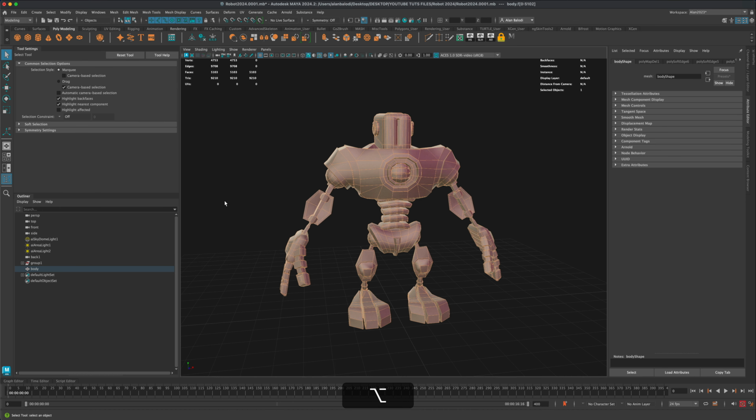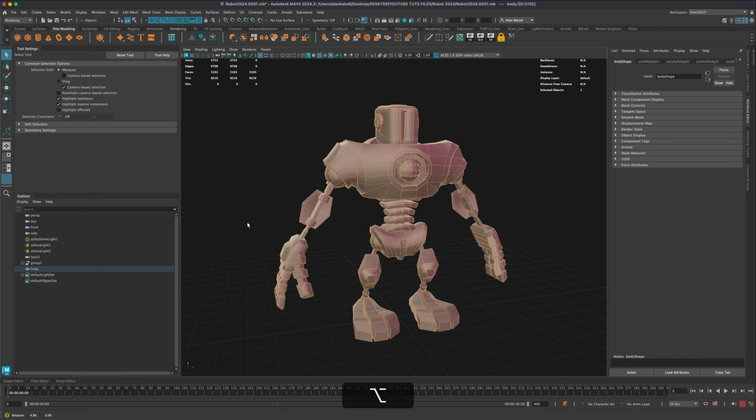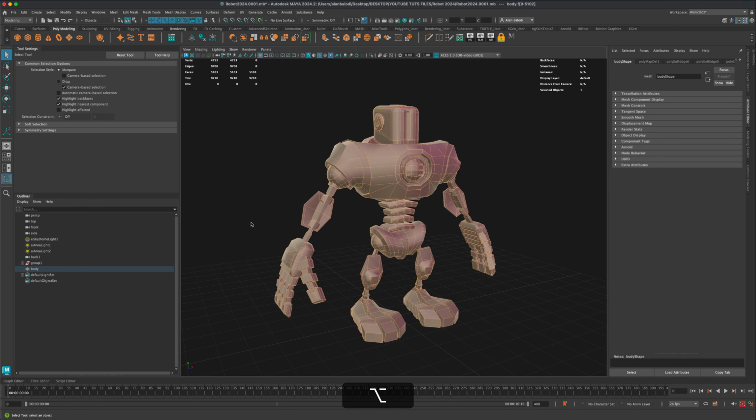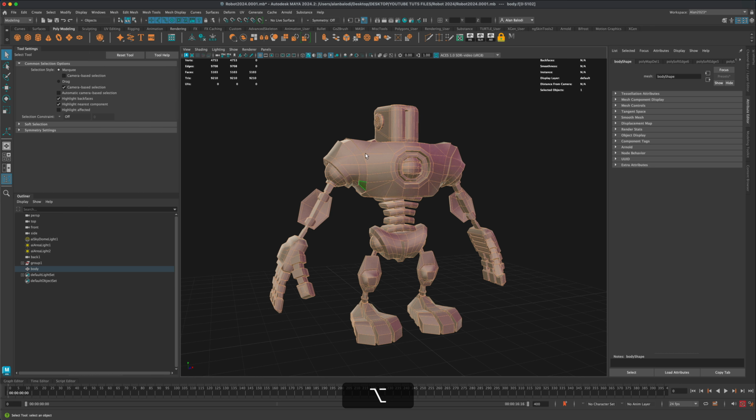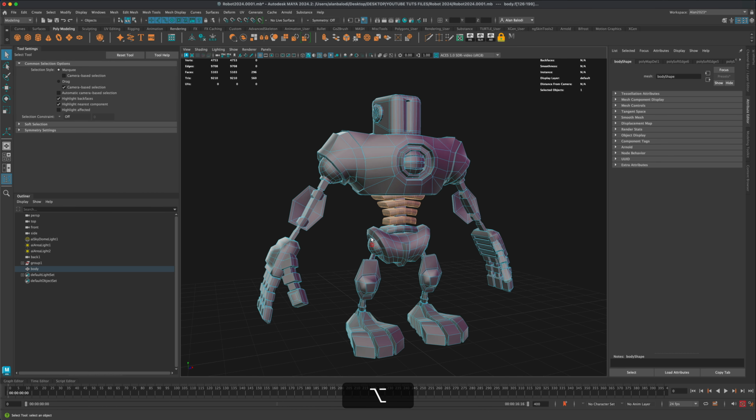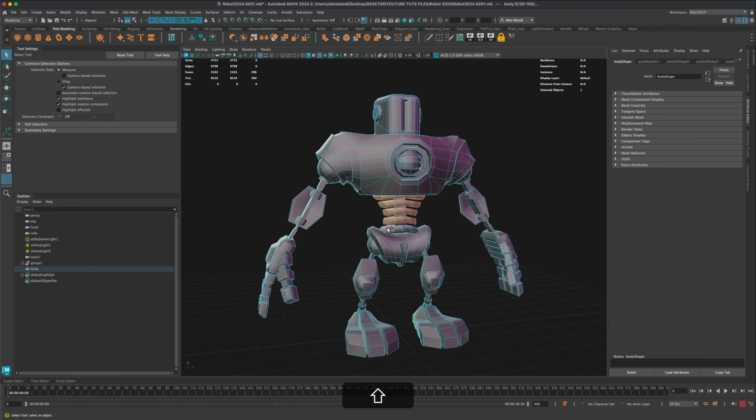The one thing to keep in mind for anyone who is new to creating UVs or game characters: even though you combine the mesh into one, you can still select each piece individually and apply different materials to it. For example, if in Unity or Unreal these pieces had different roughness or different material attributes, you can still assign different materials even though it's one mesh.